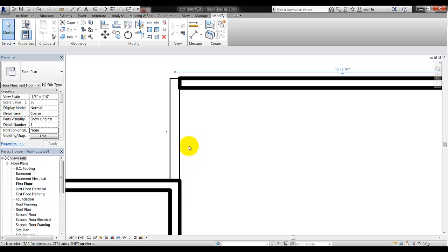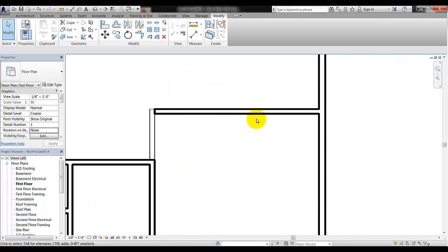And it'll show different, and it shows different because the cutting plane, that 3'6" height, is below the 4-foot cutting plane. And then same thing would need to be done over here, where I've got the wall that's at the end of the counter and cabinets in the corner here, and then this area here would need to drop down to the 3'6" as well. I'll let you do that on your own, and in the next section I'll be going over doors and windows.